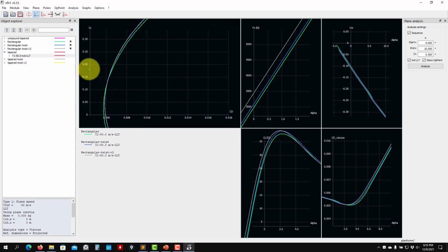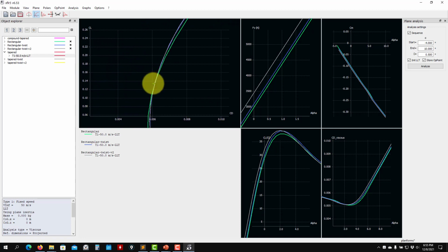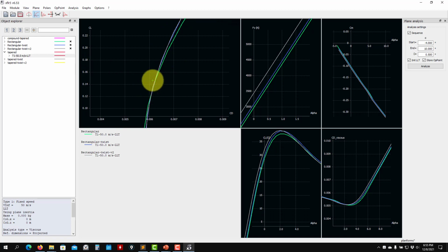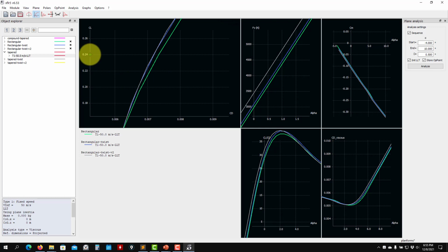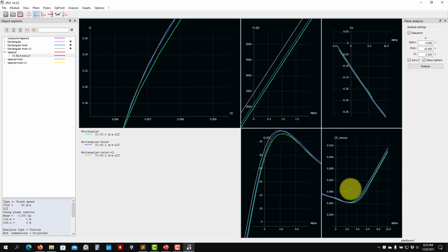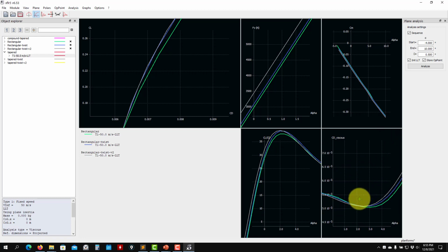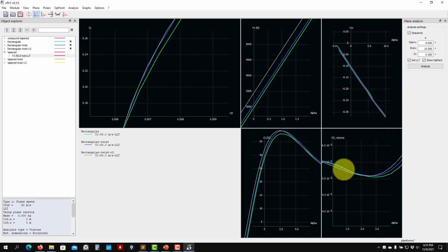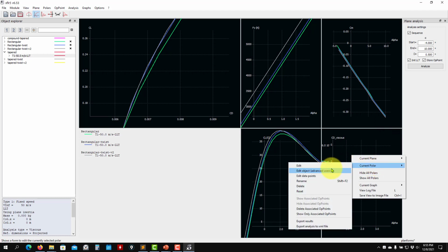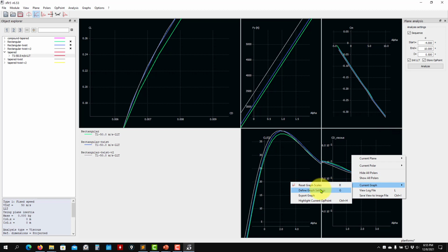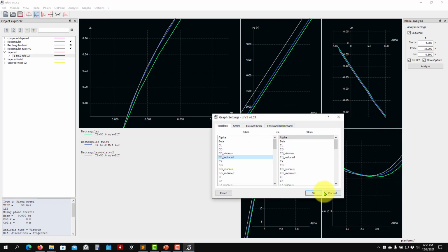So for the same lift, here we have a crossover point, meaning that here this one starts to produce more. For the same lift, you go here, for instance 0.24 for this lift, the gray one produces less, see the total. Then also you can do that subdivision using the induced drag. So here in viscous you can check also for 1 degree the gray one produces less, or we can visualize also here, let me go here, define graphic instead of the viscous, the induced drag.